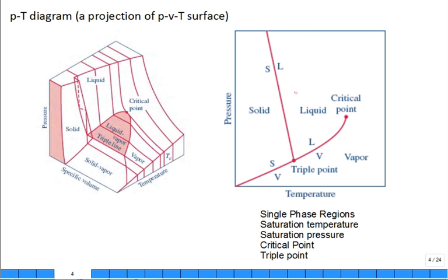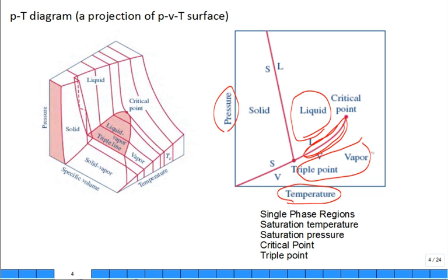This pressure temperature plot, I really encourage you to spend some time on, because now we're going to talk about the thermodynamic tables. A lot of times students don't know which table to get into. Should I be in the 2-phase table that deals with that liquid vapor transformation, the boiling, condensation? Should I be in the subcooled liquid table? Should I be in the superheated vapor table? Or should I even be in the 2-phase solid vapor table right in here? Well,